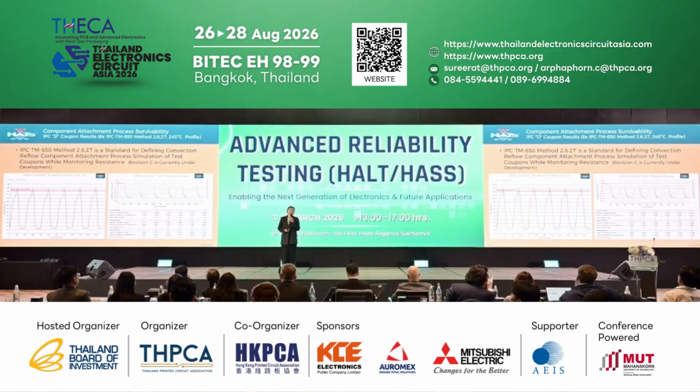This test method also requires that during the reflow, we monitor the resistance change in real time to catch any early failures already happening in the reflow process. Previously, we didn't pay any attention to the resistance change or the electrical early failures. So these kinds of failures, we just let pass.